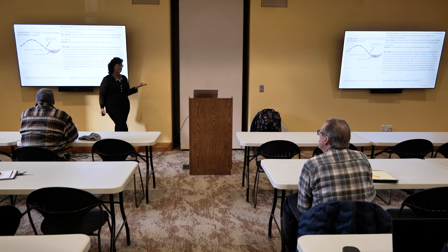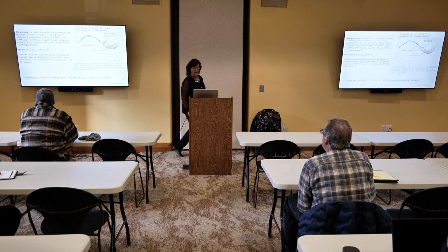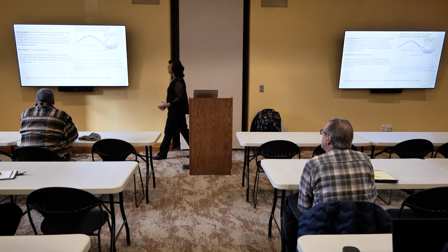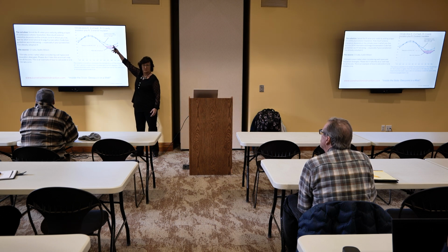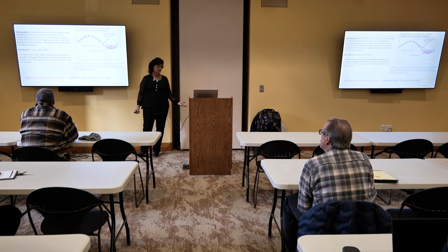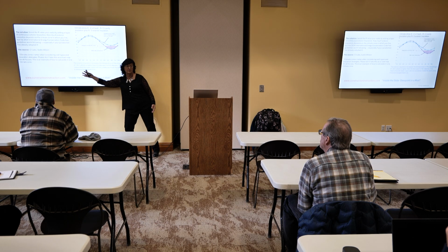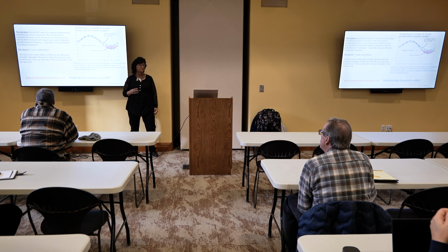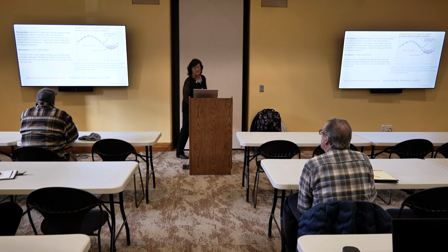I have nothing but mildew and rot. Right? I have to calculate the dew point so that I know. If I have this situation, I can put a vapor barrier on both sides. It doesn't matter. I've moved my dew point to the outside of that wall. So just some things to think about.